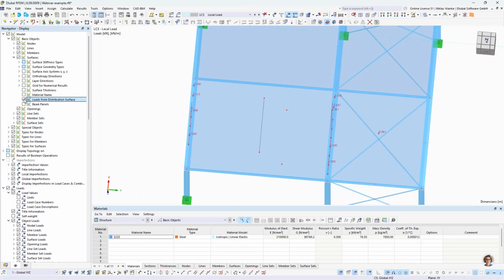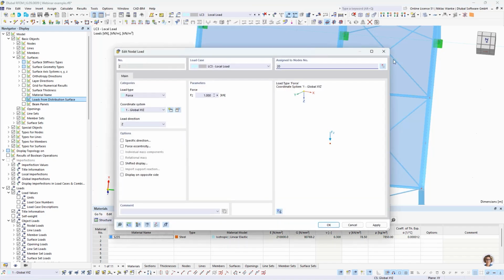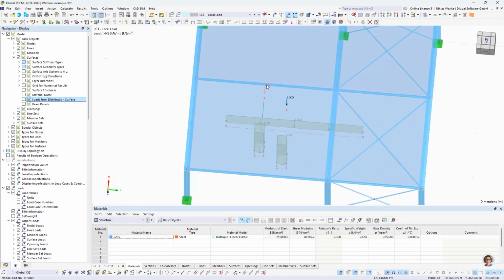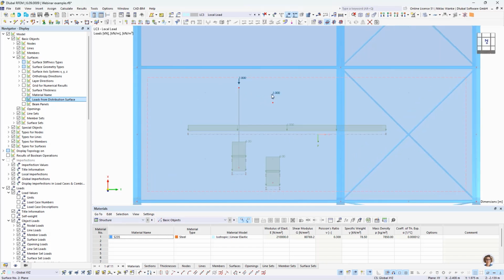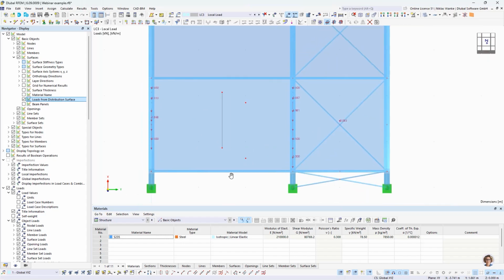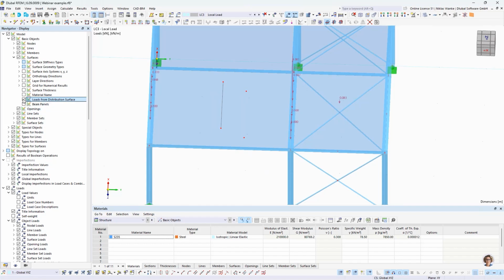And there's also one special case, because for these loads, which are nodal loads, the equilibrium is always considered correctly, also if the option is activated. So also for this load, which has eccentricity to the middle of the span, the loads are still distributed 2/3 and 1/3. But for all other loads, the equilibrium won't be considered anymore in this case.